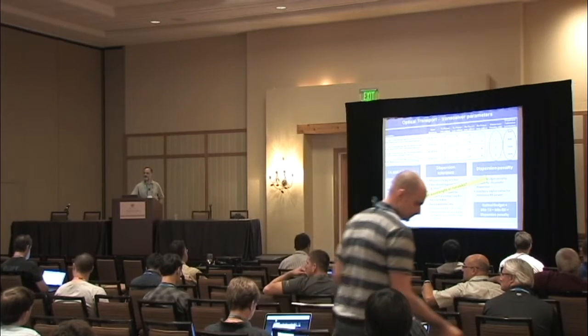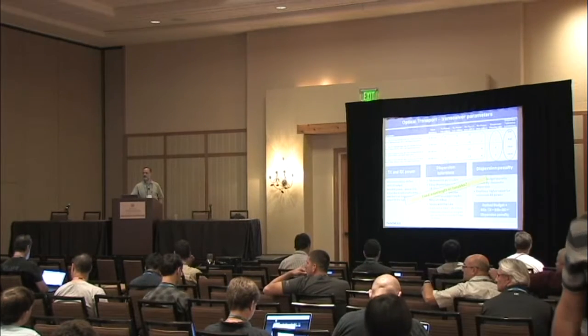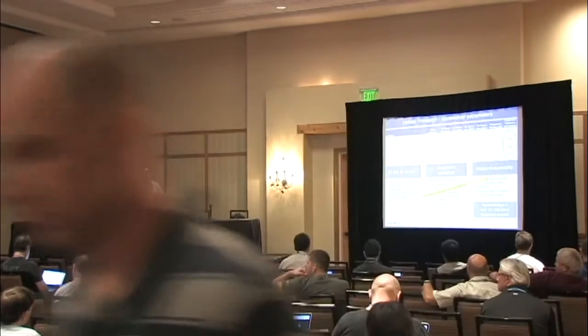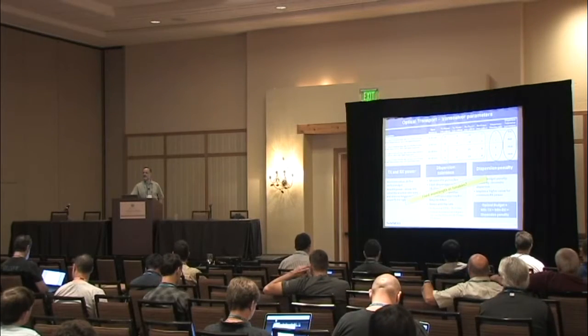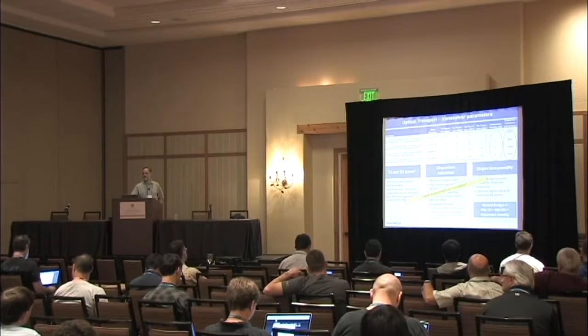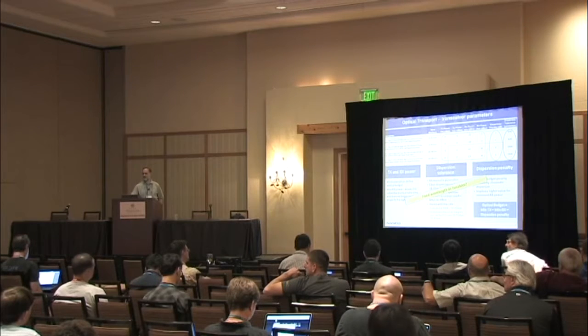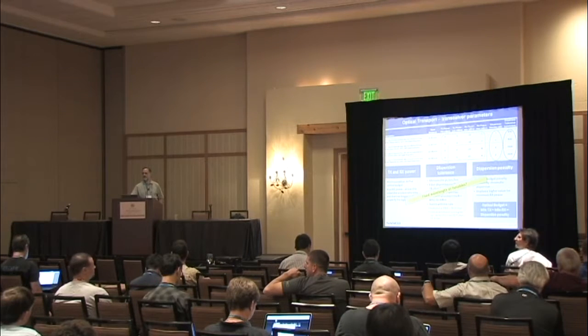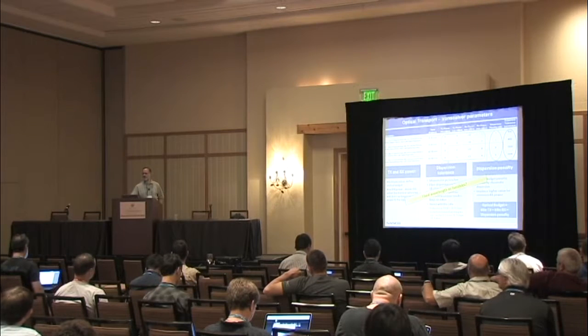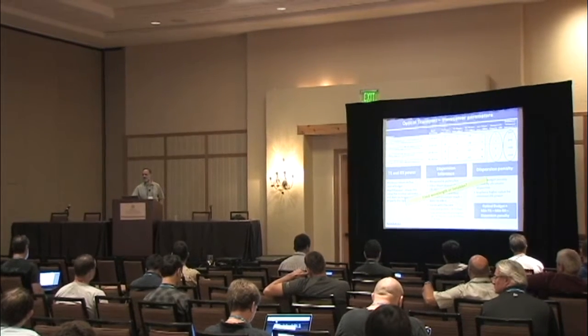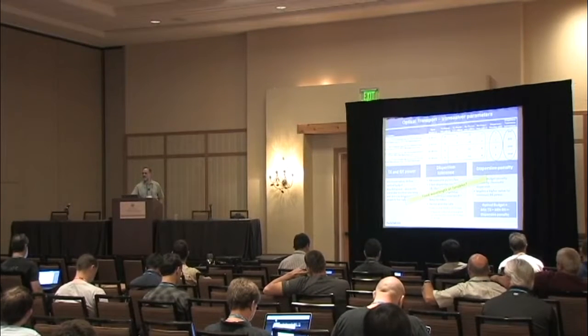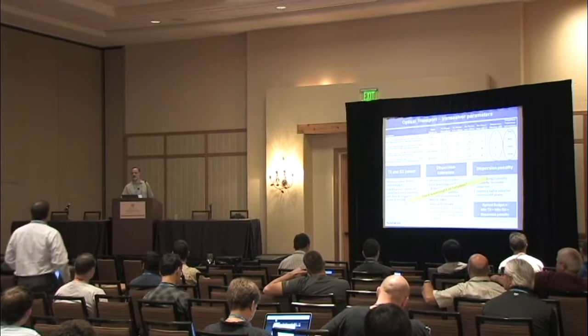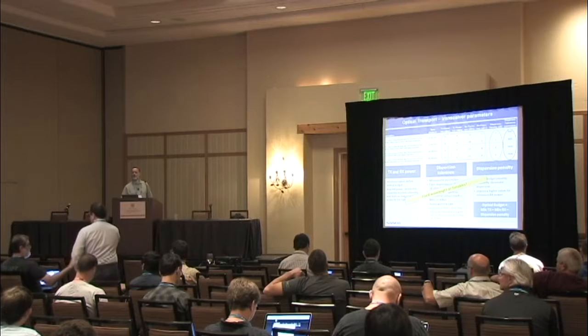The other advantage is that the tunables usually output slightly higher power and help us push the signal a little bit further. On some of the paths that we're on, either we're extending maximum distance or the only path we could get was the only path we could get, and we had to take whatever was there. Sure. Tunables in general can be amplified to about 6-7 dBs more than fixed wavelengths. So reach is an issue, yeah.